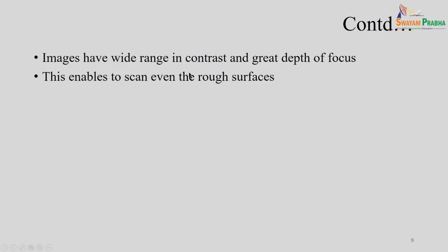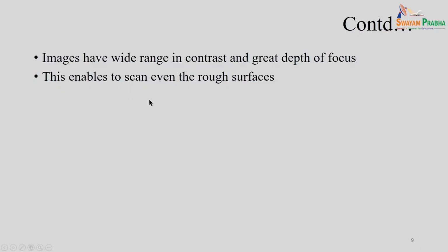So, these images have a wide range in the contrast and great depth of focus. It means it enables us to scan even surfaces with large roughness, which cannot be analyzed using atomic force microscopy, or you can say scanning tunneling microscopy. So, because of these features, even if you have roughness in the range of, let us say, micrometers, a rough surface, we can analyze using the SEM,